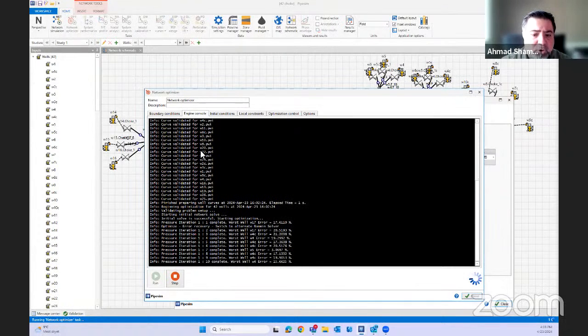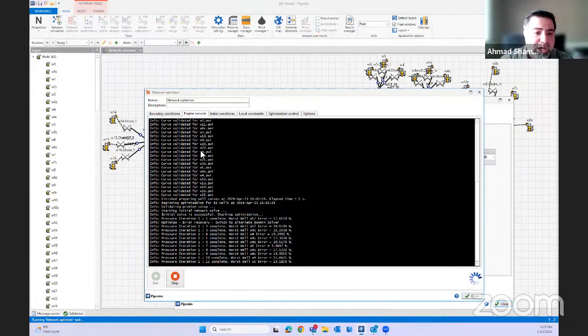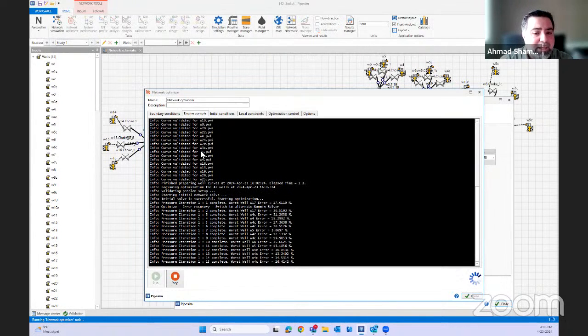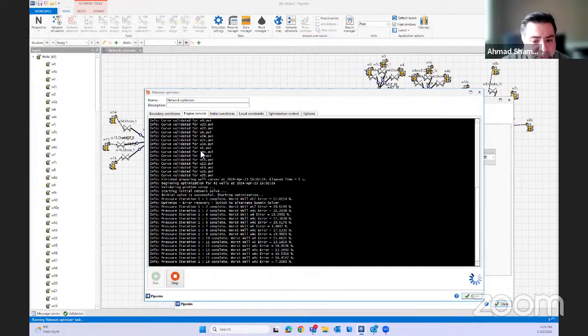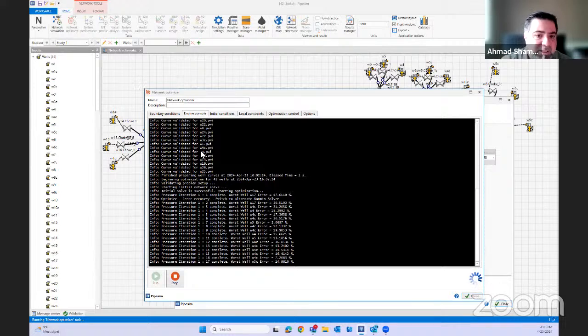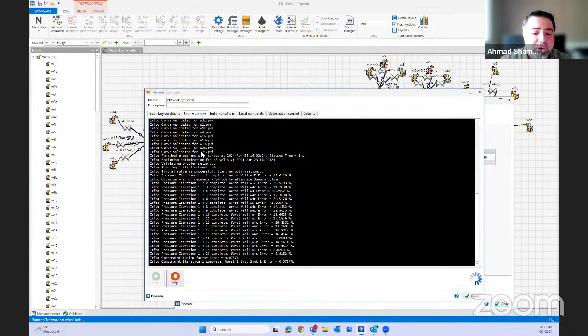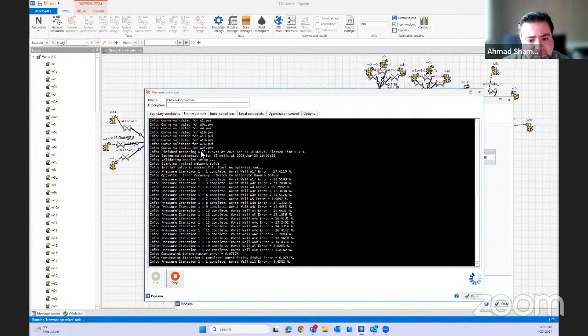Again, this is an automatic mathematical optimizer, which will try to change the choke settings simultaneously on all the wells so that it will honor my constraint, and at the same time try to maximize oil production. Obviously, I think the oil production can be affected, because I may have to sacrifice oil production in order to constrain the maximum GOR.